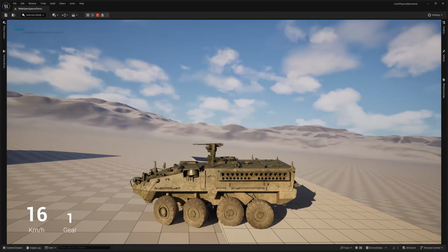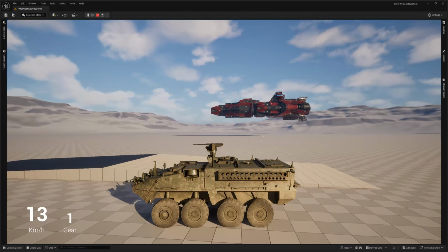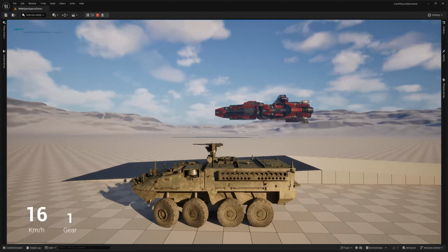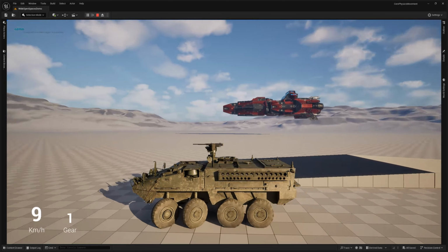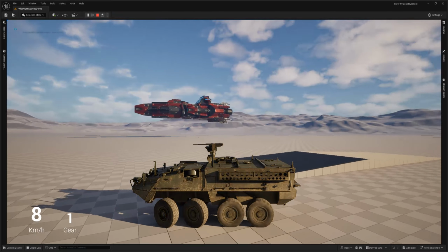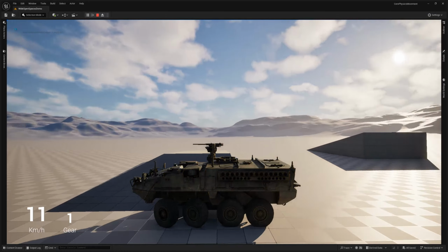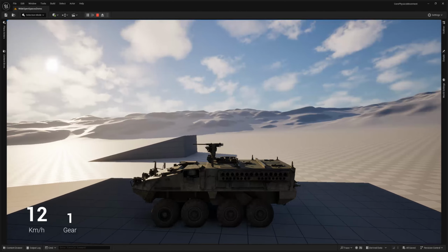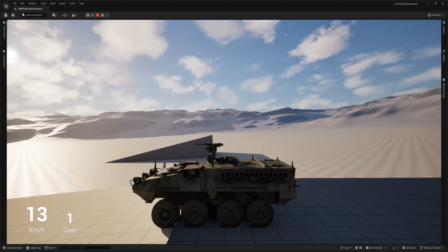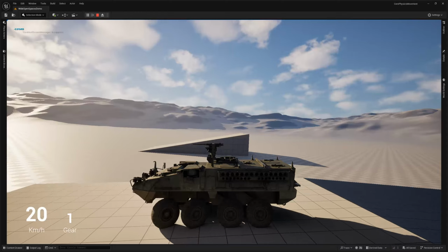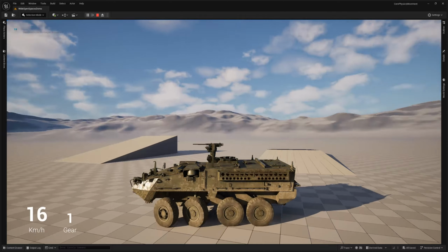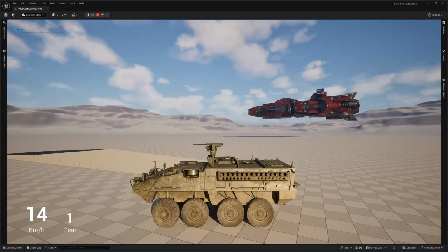So as a quick recap of what we've covered in wheels so far, we created some code to help us with center of mass, so we can get this vehicle to look like it's bouncing around a little bit more on the suspension. We created engine and transmission simulations so that we could take the accelerator inputs and turn that into angular positioning and angular velocity on the wheels.